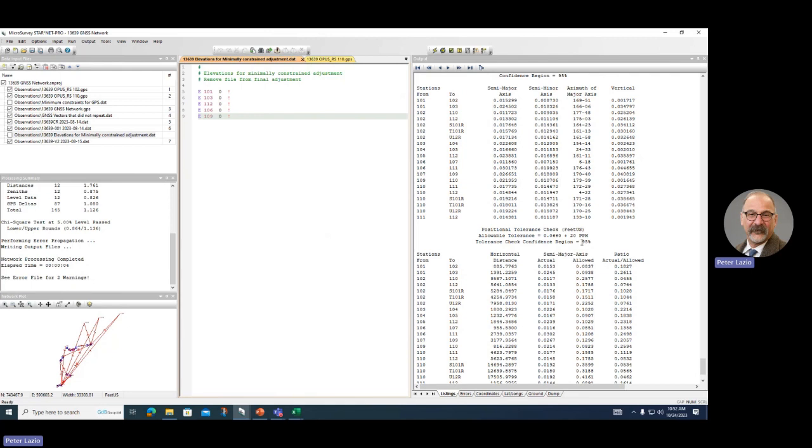So your situation, are they all GPS observations? Do you have total station data? In ours? Yeah. Ours was a traverse with statics, with the level run. It was the whole 9 yards. I think it's the station coordinate on, right? Not the relative, right? Relative. Okay, I can't remember which one, but I had to throw out some data that I thought was good because I couldn't get it past that.